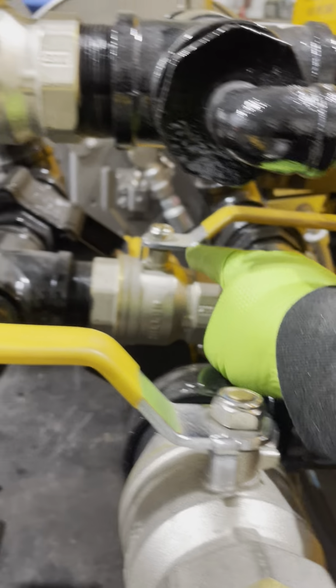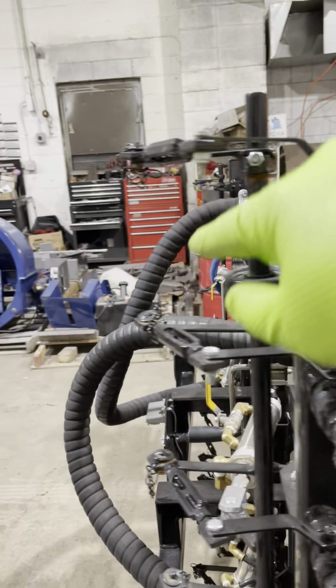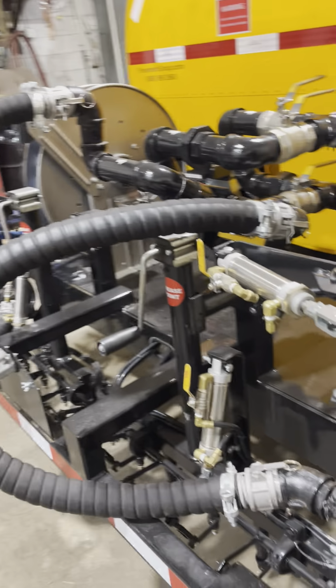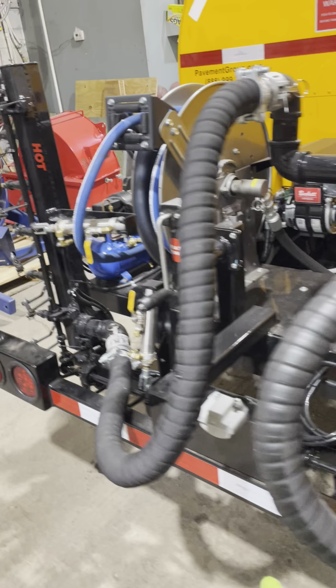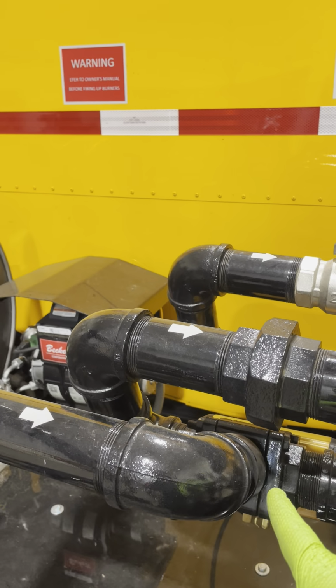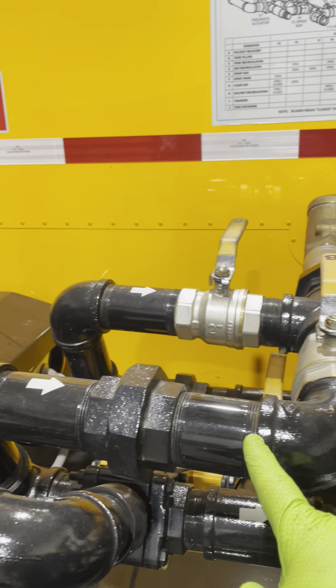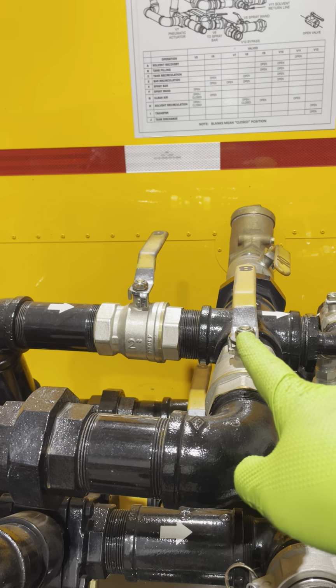So we're going to keep 6 open. Let the solvent come into the spray bar through the hose. It's going to flush everything out. It's going to be recirculating. It's coming back up this hose, coming into the plumbing. Valve 7 is closed. That's the key fob. So it's going to take a left. It's going to come up. It's going to go this way. It's going to go across to 8.